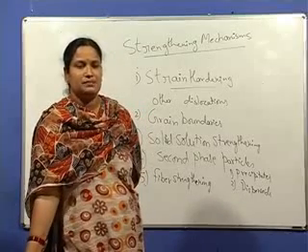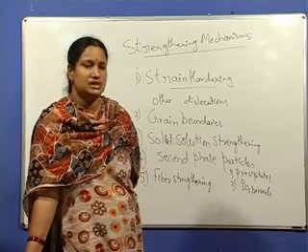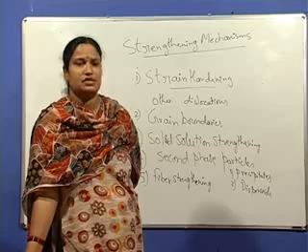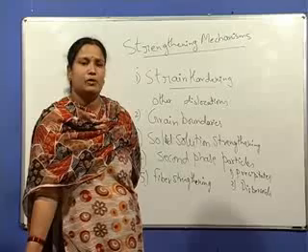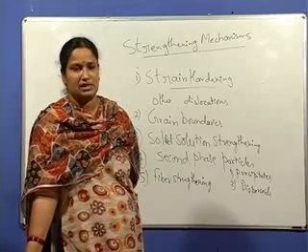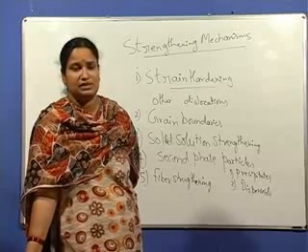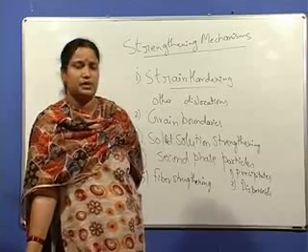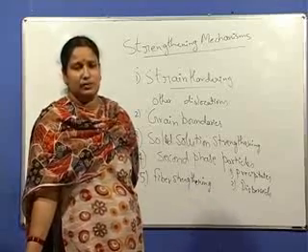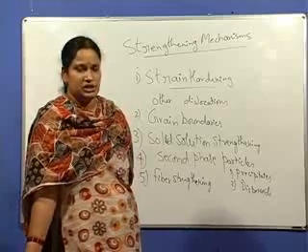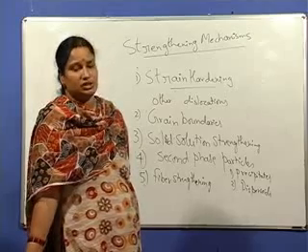So the various obstacles for the dislocation motion are, first, the dislocations themselves. Strain hardening occurs during plastic deformation, where the number of dislocations increases. As the density of dislocations increases, they themselves act as obstacles to their motion. That is the reason for the strain hardening which takes place. The second type is the grain boundary; the Hall-Petch relation was already discussed. Next is solid solution strengthening.